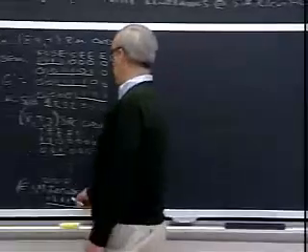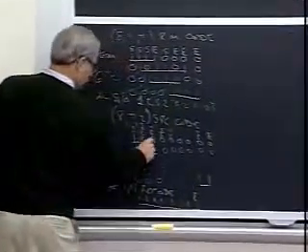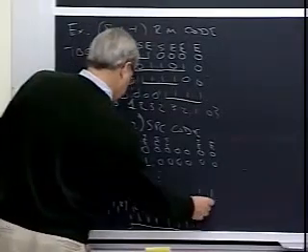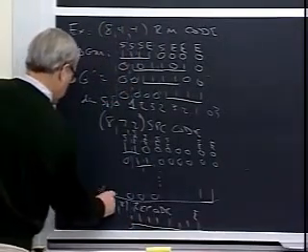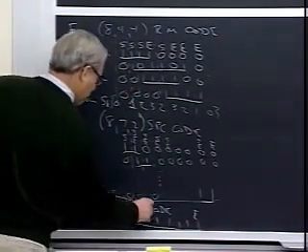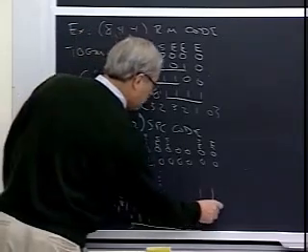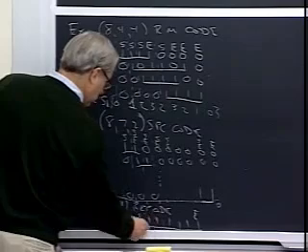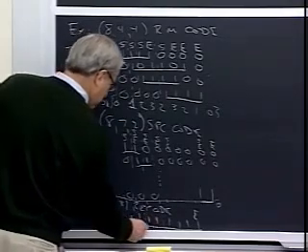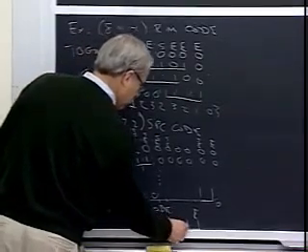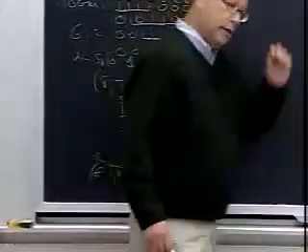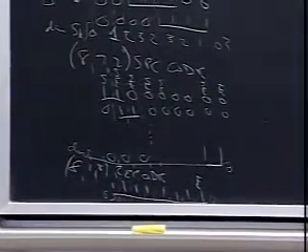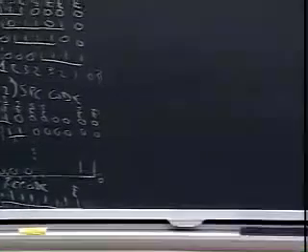And similarly down here, if we look at state space sizes, we see the dimension is going to be 1 at every time. All right, so in this case, the dimension of the state space is 0, 1, 1, 1, 1, 1, 1, 1, 1, 0. And similarly down here, if we look at the cut time, it cuts 1 active generator at every time, so it's 0, 1, 1, 1, 1, 1, 1, 1, 0. So we get at least the state space dimensions just by inspection of the trellis-oriented generator matrix.